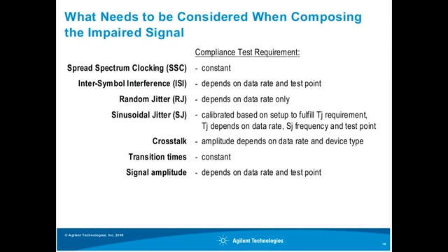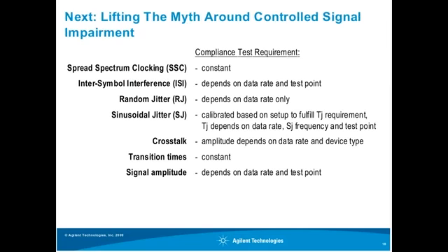So, in summary, there are different jitter tolerance curves, and there are different test points, and now there are different stress components in a signal which are added together to stress the receiver or to stress the receiver in a sync. These components are summarized here.